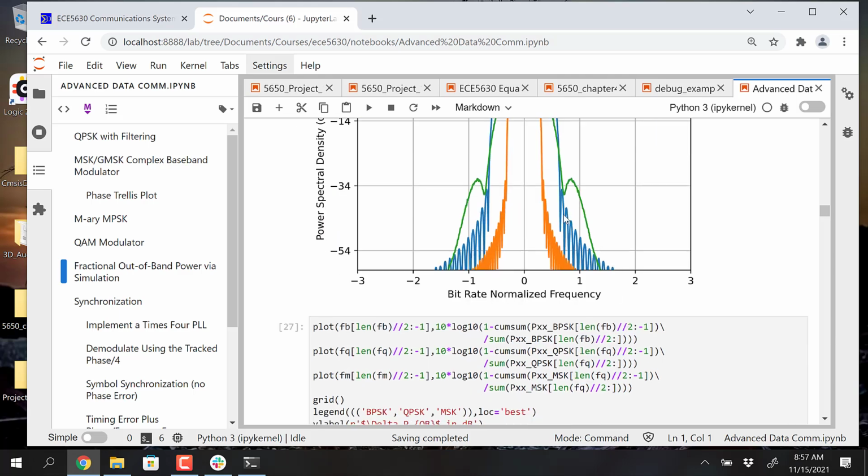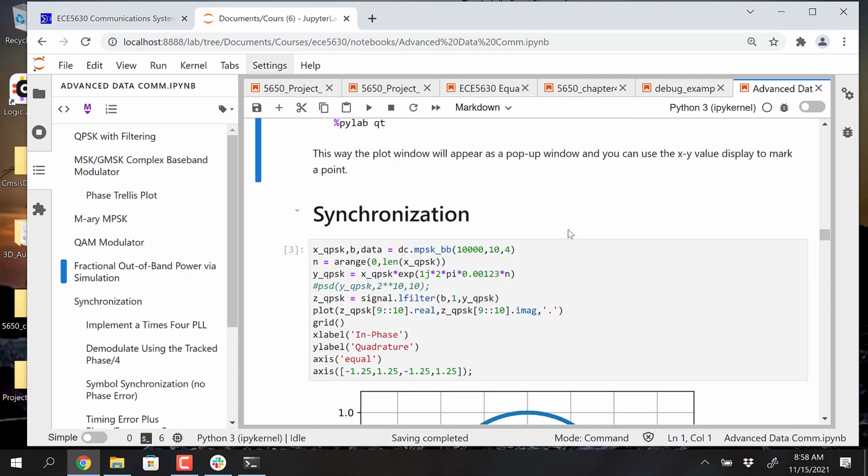And of course, true raised cosine or square root raised cosine would not have any of these side lobes. It's because it's got the underlying sinc function, which is a non-causal pulse shape, but it's been truncated, and I didn't apply any window, so the truncation has caused the side lobes to occur. But it actually would just go straight down, right? And then it's absolutely 0.